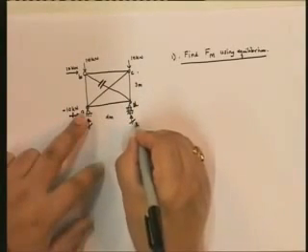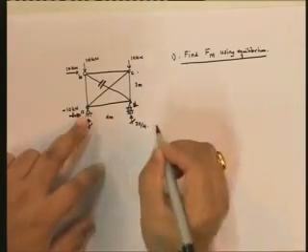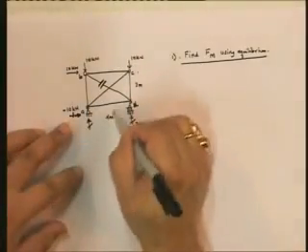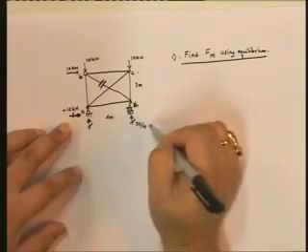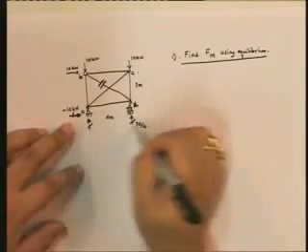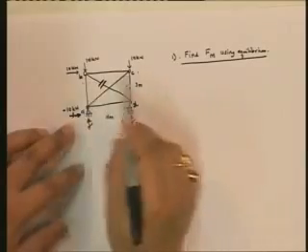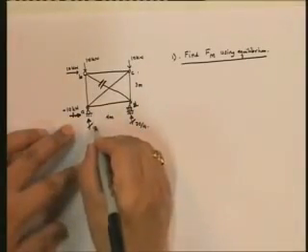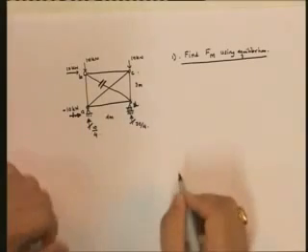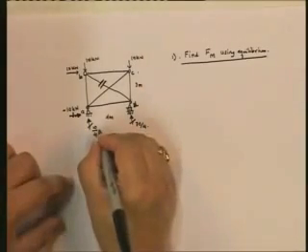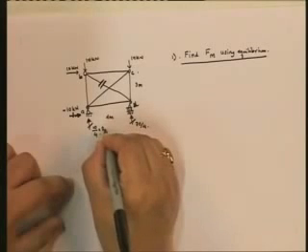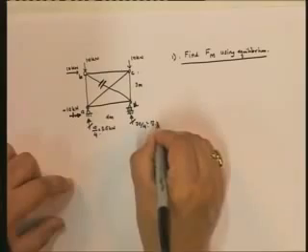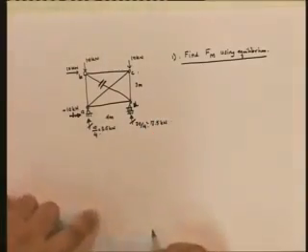So this is going to be equal to 70 by 4 value, because 10 into 3 plus 10 into 4 is going to be equal to 70. 70 divided by 4 is 70 by 4. And now since this plus this is equal to 20, this is going to be equal to 10 by 4, which is equal to 2.5 kilonewtons, and this is equal to 17.5 kilonewtons.